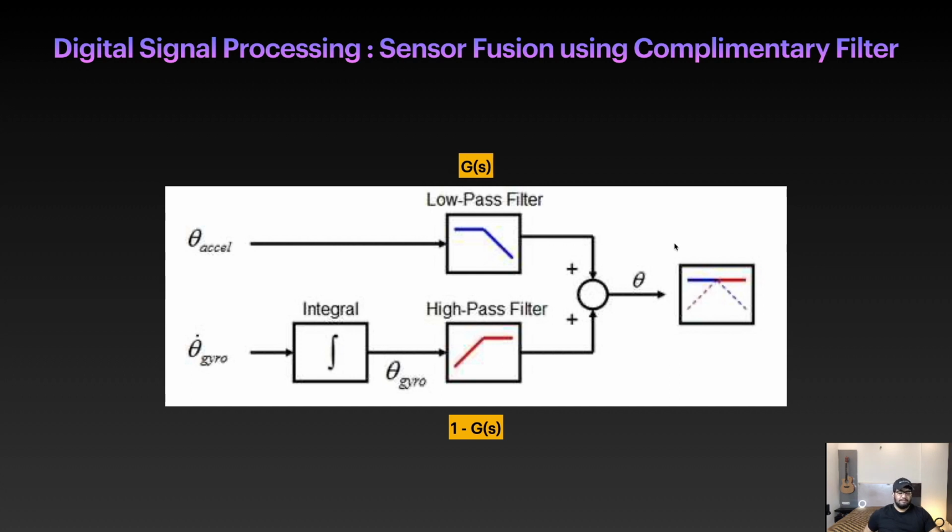You can see this excitement because when you actually implement this, it's a very powerful concept and very easy. Even for microcontrollers like the Arduino, you can implement complementary filters with some libraries. There are some open source libraries which help you implement a complementary filter, and if you are into that, I would highly recommend you do that and see for yourself. Again, this is called sensor fusion, and at the end you get a useful value: an estimated degree of one particular axis, which you can definitely use for your advantage. So that was called sensor fusion.